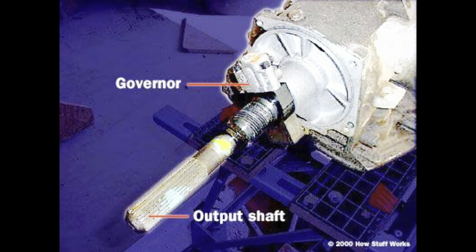The throttle cable simply monitors the position of the gas pedal through a cable that runs from the gas pedal to the throttle valve in the valve body. The vacuum modulator monitors engine vacuum by a rubber vacuum hose which is connected to the engine. Engine vacuum reacts very accurately to engine load, with high vacuum produced when the engine is under light load and diminishing down to 0 vacuum when the engine is under a heavy load.